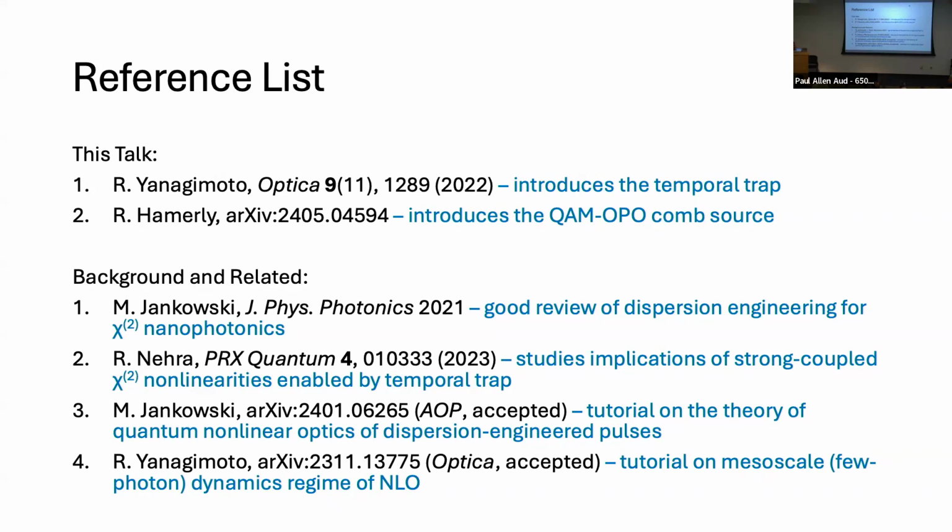Because of that, your coupler design is significantly easier than what Amir has had to do for the efficient SHG or OPO experiments, where you have to couple out both frequencies. In that case, if you just use a standard directional coupler, if the trap field is at a longer wavelength, it'll couple out much more efficiently.